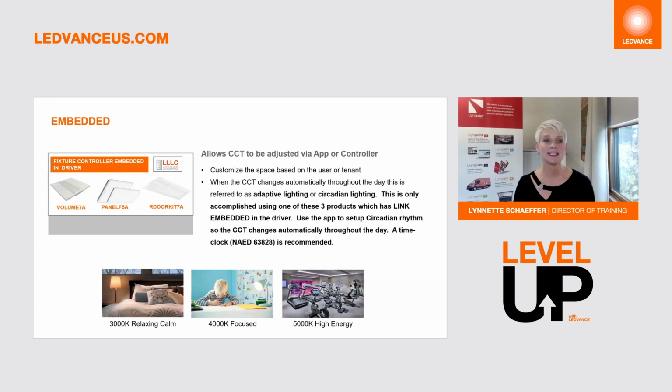So how about if you're using the fixture controller that's embedded into the luminaire? What specifically sets these three luminaires that you see here apart from all the other things that we're talking about is that these specific three have the fixture controller embedded in the driver, and that allows for the CCT to be adjusted via the app. So no more having to take the luminaire out of the ceiling and flipping a switch to change the CCT. These three luminaires, the volumetric or the volume 7A, the panel 5A, and the retrofit door kit 7A, all have the fixture controller embedded in the driver. And of course, this is as of October 2024. I'm sure we're going to be introducing a few more that are like this.